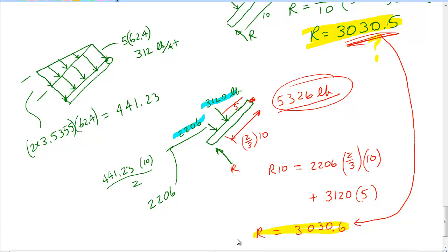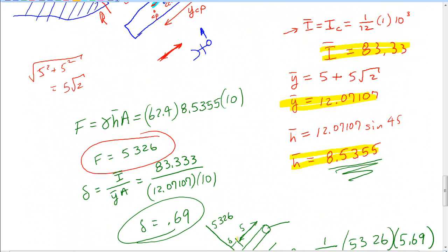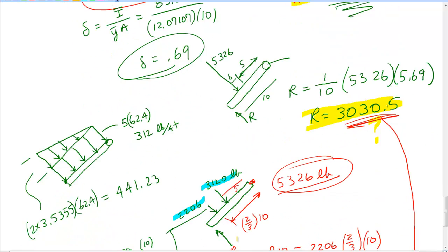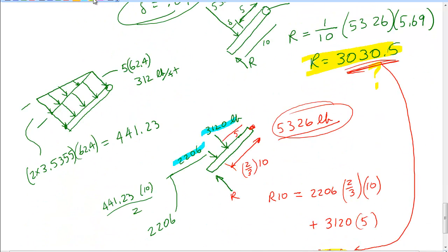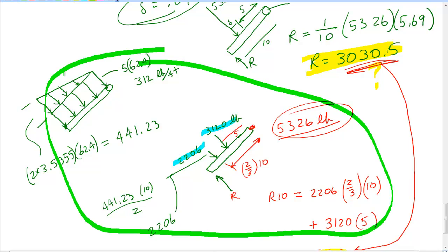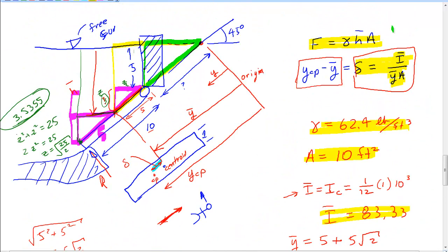So we can see that for a square gate, either one of these works. And on the test, that's what we're going to deal with, this square gate. We're going to come back and take a look at this, and I'm going to also give you possibly a problem that's not impossible, but incredibly difficult to solve this way, which leaves you back to solving the problem using these simple 2 formulas right here.